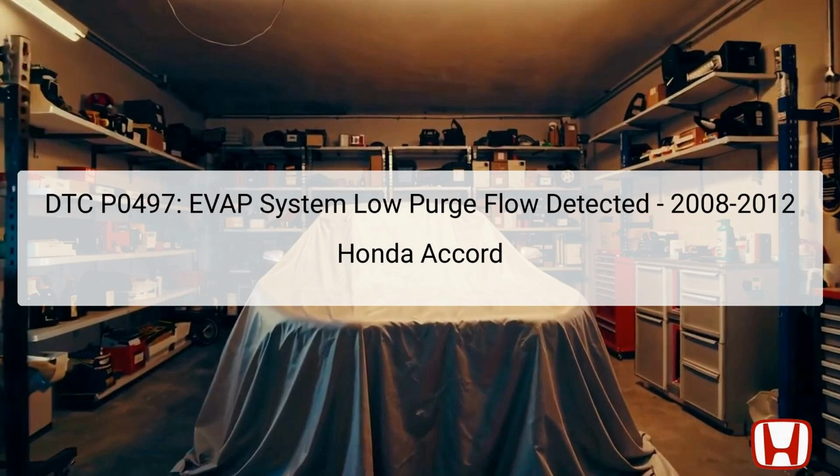The key components involved in this process include the EVAP canister, which stores fuel vapors, the purge valve, which regulates the flow of these vapors, and the vacuum hoses connecting these components. Typically, the EVAP canister is located near the fuel tank, while the purge valve is positioned along the intake manifold. If not addressed, a P0497 code can lead to decreased fuel efficiency, increased emissions, and potential inspection failures.